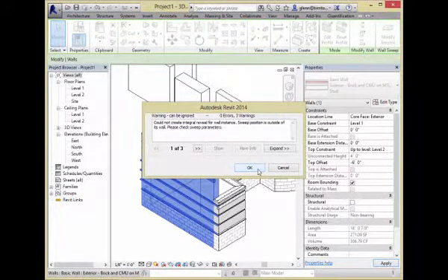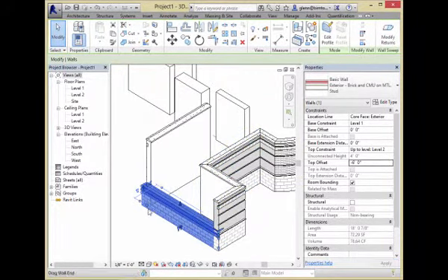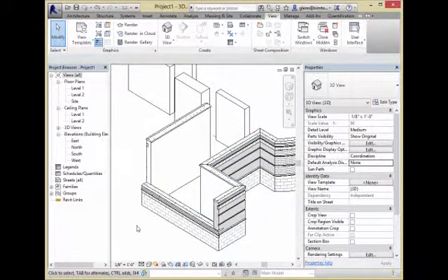That's okay. This is a very complicated wall, so there's all these little reveals and stuff in here. It's complaining that if I make the wall that short, it won't be able to do them all. And I'll just say okay to that for now. It's a very short wall right now. But the groovy thing about doing this with offsets, as opposed to manually putting in a height, is that if anything happens where level 1 or level 2 changes, that offset will always be honored.